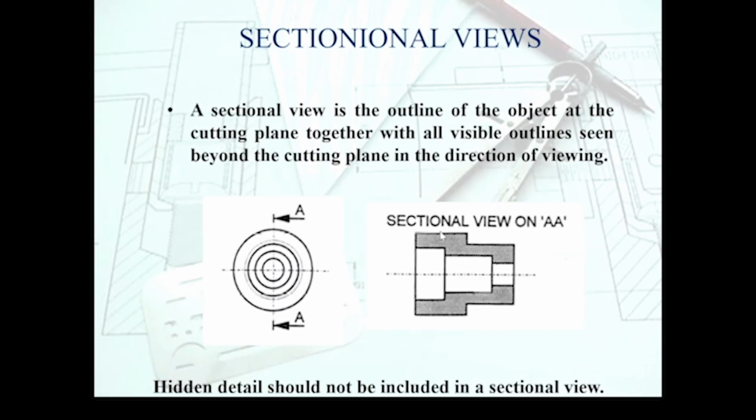However, the one which is common in engineering is producing a sectional view, one with AL, which actually shows the material that's been exposed and the remainder of the part that's hiding behind it. That is included. So it's basically half the part in this particular case, and as you can see, the insides were revealed to show the different steps. So we can now safely put in diameters in here, and all the lengths, without breaking any of the rules.